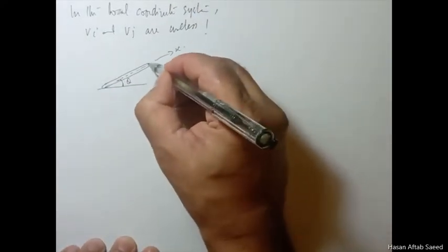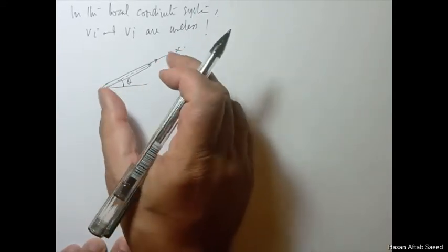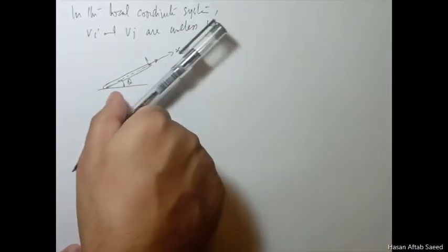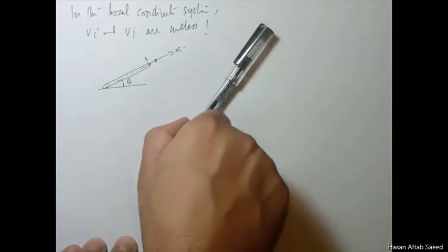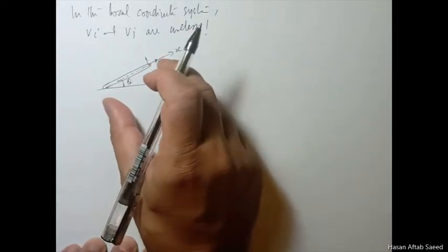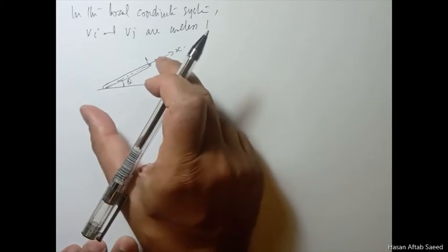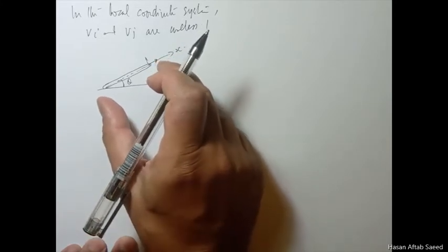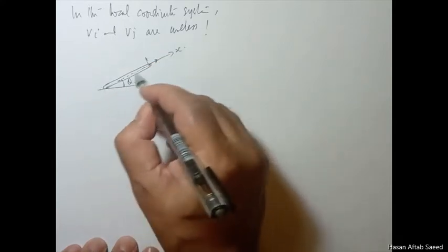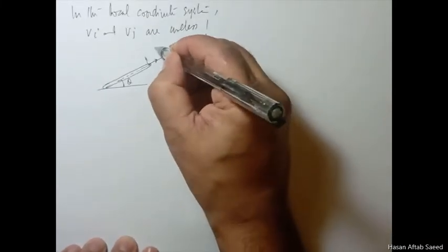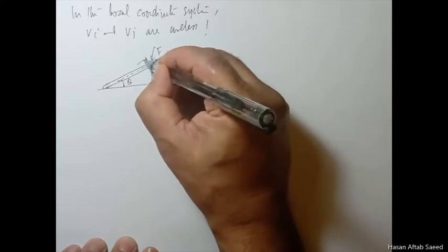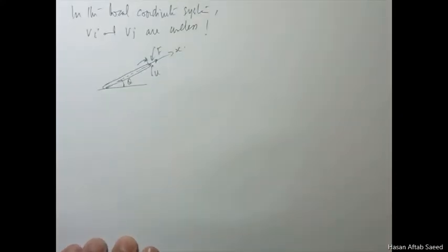So here this displacement is of importance because it is either stretching or it is contracting. But if it moves in this direction, obviously it will just be a rotation. It has nothing to do with the stretch or elongation of this element, because remember that it's a linear element, axial element. So there's no deformation perpendicular to its axis. All the deformations are in the axis. So any meaningful force is also in this direction. Any displacement is also in this direction. Forces and displacements in this direction are meaningless here.